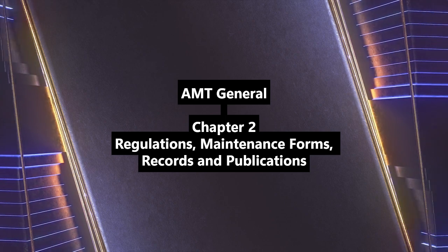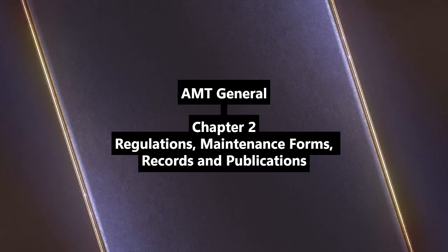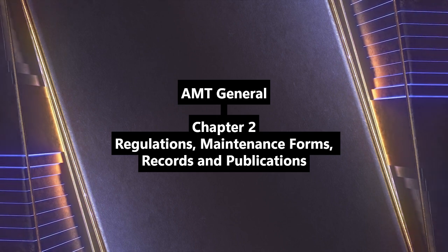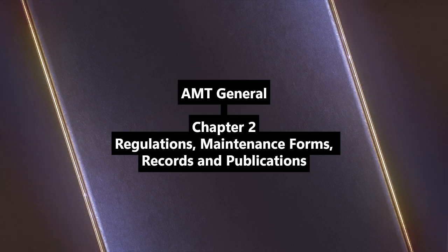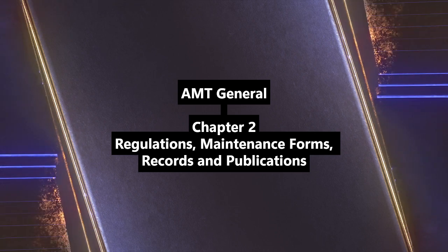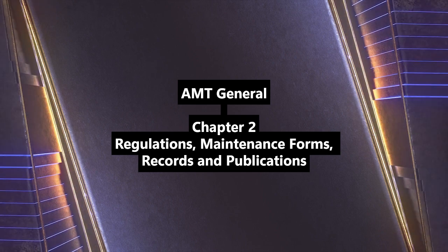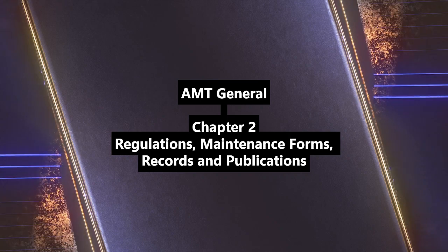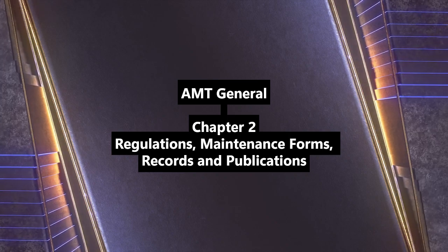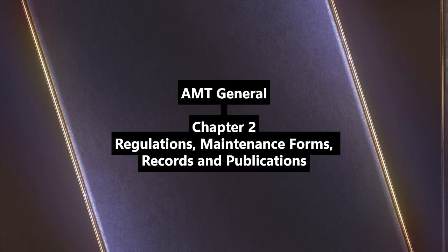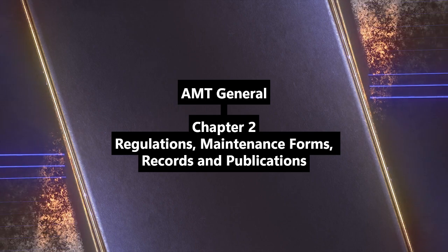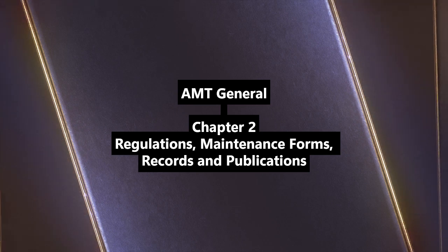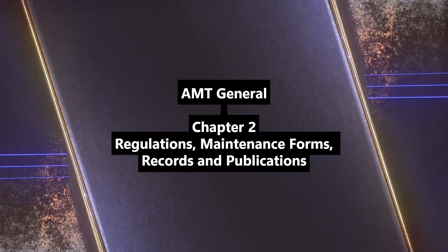Okay. And you mentioned airworthiness has 2 main phases. Broadly speaking, yes. Original airworthiness, that's getting it certified from the factory. And recurrent airworthiness, that's everything you do to keep it airworthy throughout its life. So the initial setup versus ongoing upkeep. Exactly. And that original airworthiness piece, getting it certified initially, that's really where 14 CFR Part 21 shines. Part 21, okay. And what are the other core regs? The 3 big ones are Part 21 for certification, Part 43 for maintenance, and Part 91 for general operating rules. 21, 43, 91.